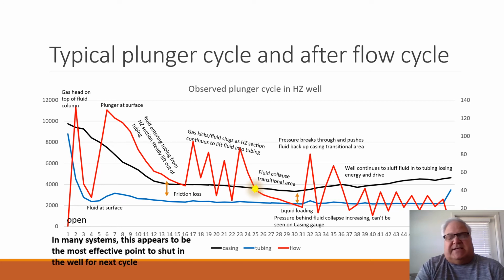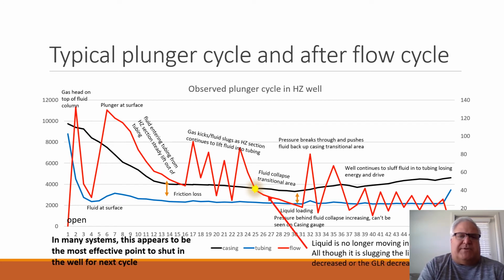This is kind of another interesting thing. When you're trying to run a plunger lift, and I've said you've got to start reacting much sooner than the tubing critical rate or liquid loading and a tubing critical rate. So how do you make that effective with a plunger lift? So if you use kind of the old rule of thumbs, here's a plunger well, it's shut in.